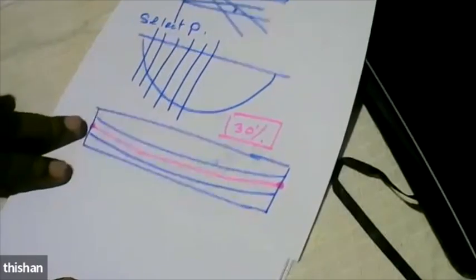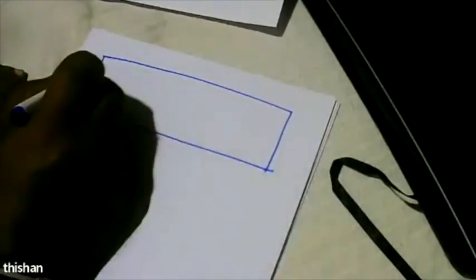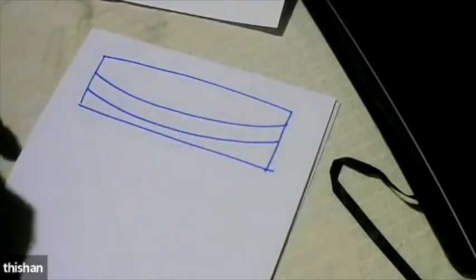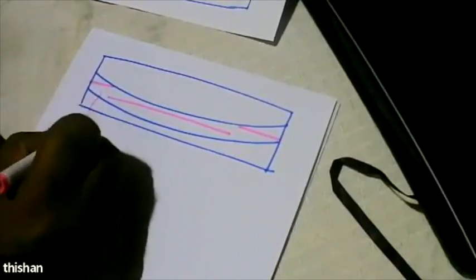But then we also can have another option, and we say we are not going to go for post-tensioning, we are going to go for pre-tensioning, and we might have a straight cable like this, and another cable like that, and here we shift the centroid by debonding.